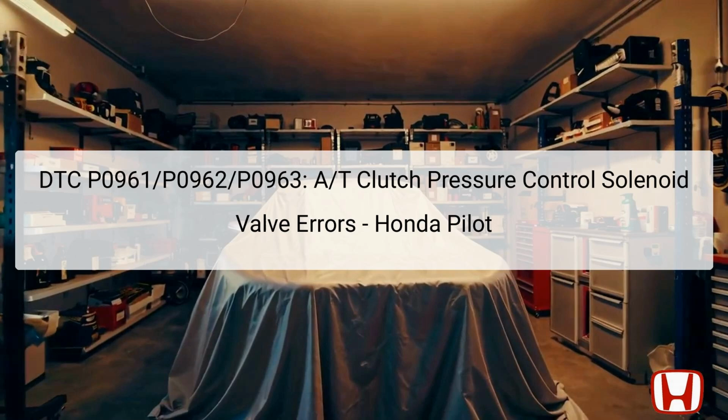The solenoid valves are critical components that manage the hydraulic pressure for clutch engagement, ensuring proper shifting and overall transmission functionality. Notably, these errors are linked to electrical circuit problems rather than mechanical faults within the transmission itself. Understanding the nuances of these error codes is vital for appropriate diagnosis and repair. In the upcoming slides, we will delve into detailed descriptions, possible causes, symptoms, and systematic troubleshooting steps.